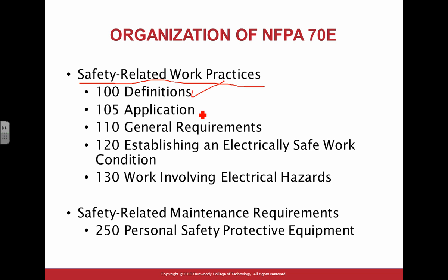Then the applications, how to apply them. Then general requirements, we'll spend some time on that one. Establishing an electrically safe work condition. That's where you guys come in. This is a fancy name for putting the equipment in a safe working condition by de-energizing it, verifying that it's de-energized, and doing the lockout tagout procedures that you guys know. So putting the equipment in an electrically safe work condition, that's the term that they use.